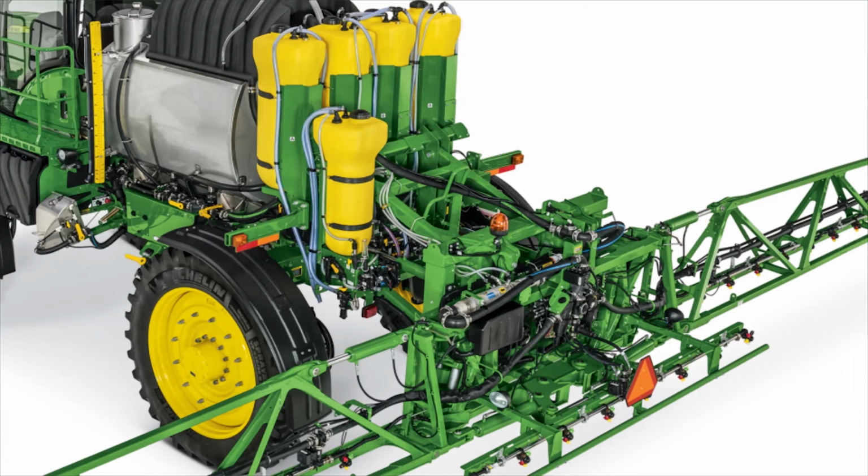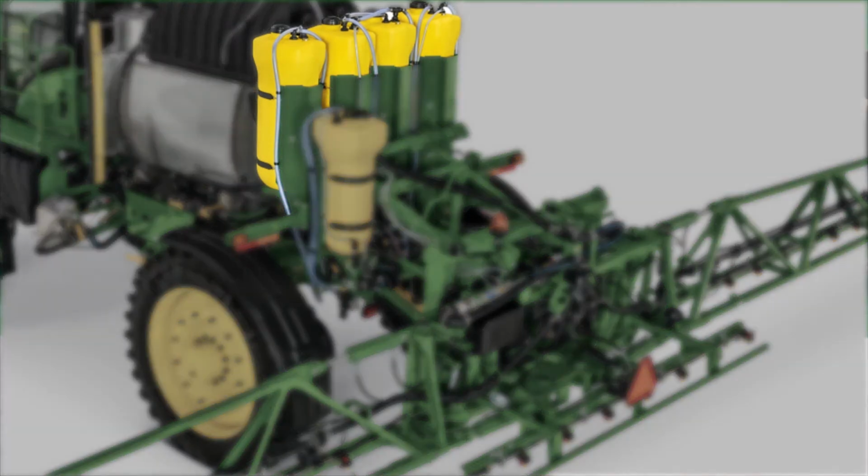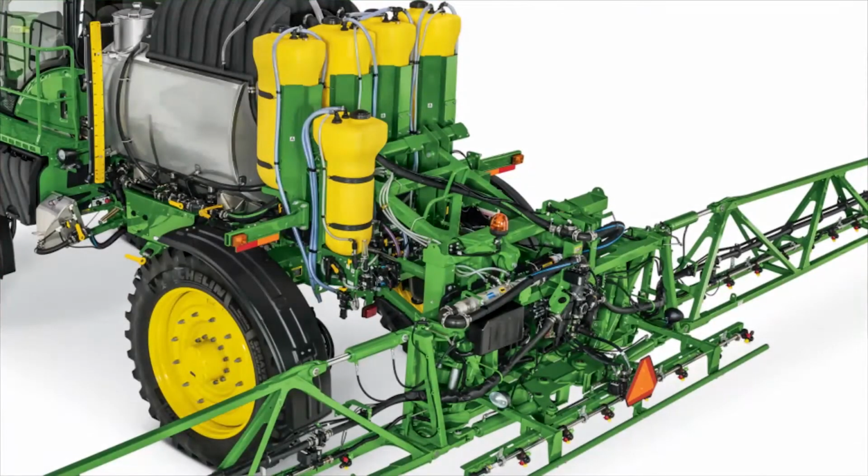The direct injection system we use for our John Deere sprayers is a system made by Raven Industries. We do have the option of carrying up to 235 gallons of concentrated chemical, which is basically distributed between 4 tanks that are 50 gallons and then a 35-gallon tank as well. We have the option of putting on 3 separate direct inject pumps, and any combination of those. You can have 1 pump, 2 pump, or up to 3 in a high flow or a low flow variety.